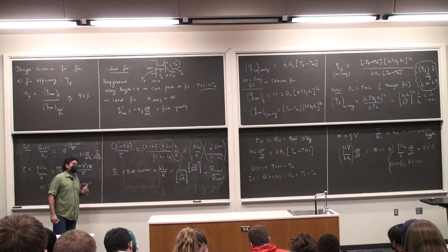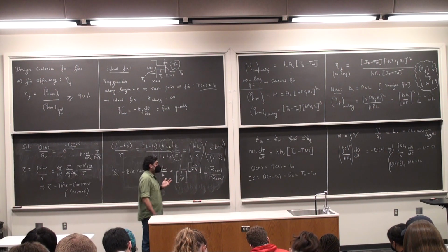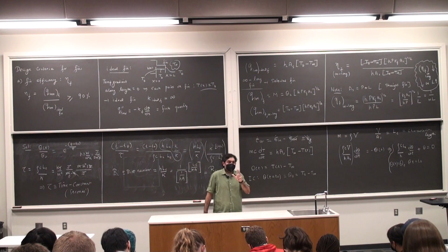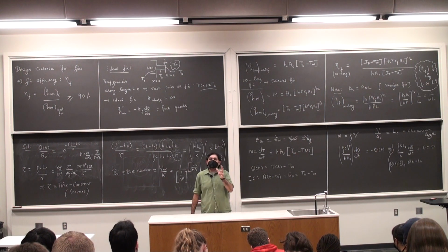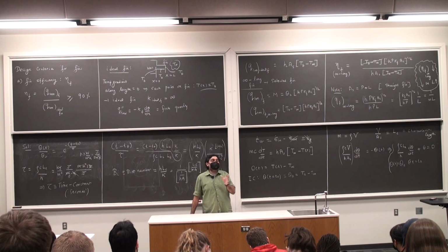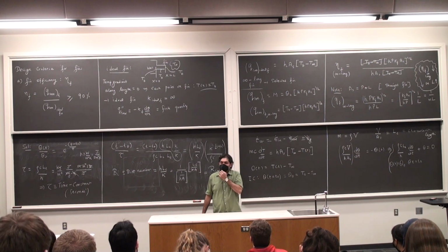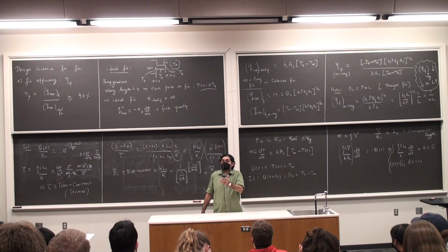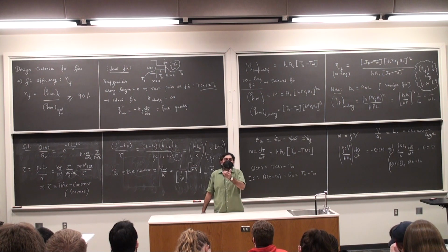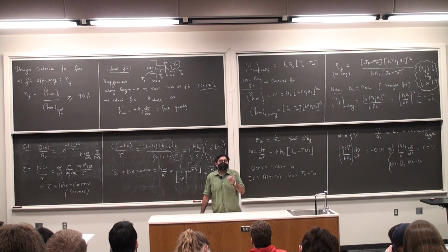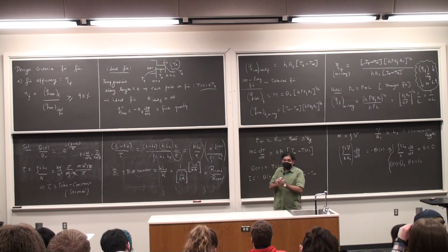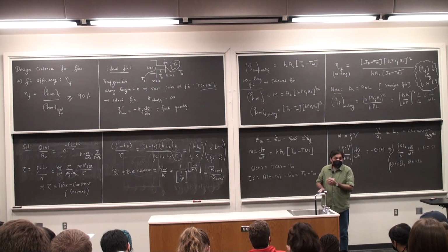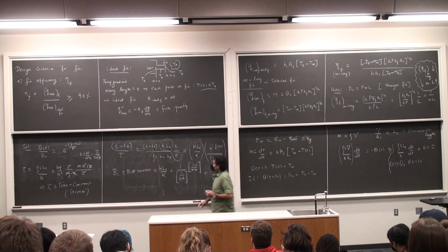And you would have typically come across in system dynamics that the Biot number has to be really, really small, which means that there is no thermal resistance to conduction, approximately 0, which means that the temperature gradient is essentially 0. If there is no resistance to conduction, there is no gradient within the body. And that's where the Biot number being small comes into play, but we are not there. We have to look at what the physical dimensions are. But keep this in mind.